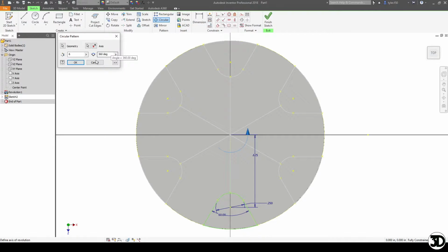Now you choose the pattern itself to be about, let's say 360 degrees, which is a circle. I could say 180, so it only patterns at about 180 degrees, or so on and so forth. So you have to really figure out your angles that you want to pattern it about. Alternatively, you can also suppress features. So one great thing with doing this style is you could suppress, let's say, one feature, but keep it spaced at, let's say, 6 geometries. So that's one thing to note.